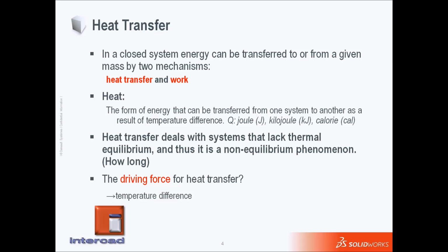Note that if we have an open system, mass could also bring energy in and out. So our job is to find the equilibrium state by saying how much energy is coming in, how much energy is going out, how the energy of the system has changed, and whether the system is in an equilibrium state.